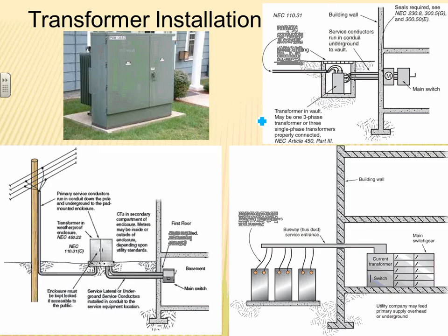So that's, I thought, just important. Here's a couple of examples, guys. You probably have installed a bunch of these. We talked about this one. If your system is, I believe it's 400 amps, if you're higher than 400 amps, you must, correct me, 400 amps or higher, you have to have a termination box.